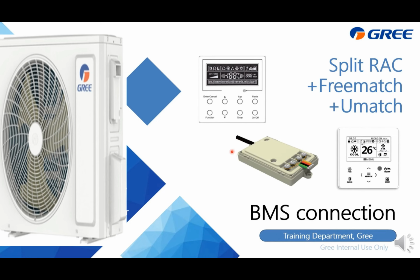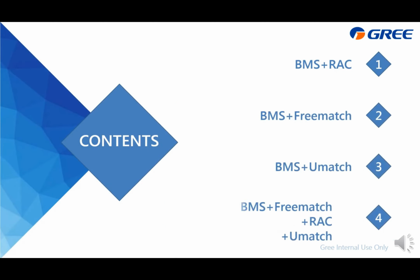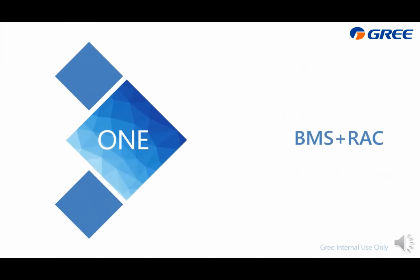This time, we're going to talk about how to connect Gree light commercial air conditioners, including split residential air conditioners, free match, and U match, to the PC, which is the BMS system. According to the indoor units, we divide this presentation into these 4 parts. First is to show you how to do the wiring from the residential air conditioner to the BMS system.